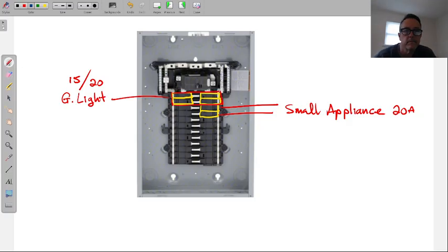Can't you just jam some pennies in it? No, again, you could, because what did I know about that panel? What I knew about that panel is every one of those breakers is barely being used. I measured the amperage on every one of those 20 amp breakers. Most of them have 0 on there. Some of them had 2 amps. When I measured the amperage on the main, it was 25 amps. That's how much amperage was in use in the house. So I knew that people just kept adding breakers to this for minimal usage requirements.